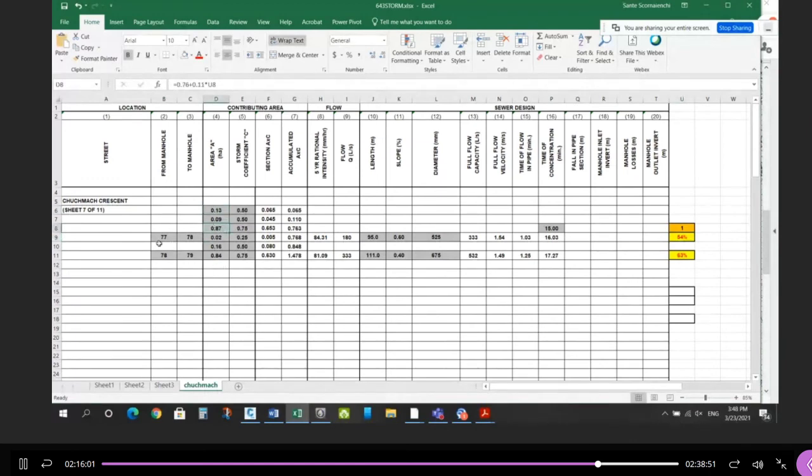So now I've increased the area going to this pipe. What happened to the capacity? Well, this number goes up, right? The expected flow is bigger. There's more area. But how does it compare to the pipe capacity? Well, look at what happened to the percent full. So when this is 0, and I'm just playing games with the math, you can actually type the number in, right? You don't have to add it the way I did. But if I take the 0.8 and add 0.5, you get 1.3. And if I add 7.6, if I add 1.1, you get 8.7, right?